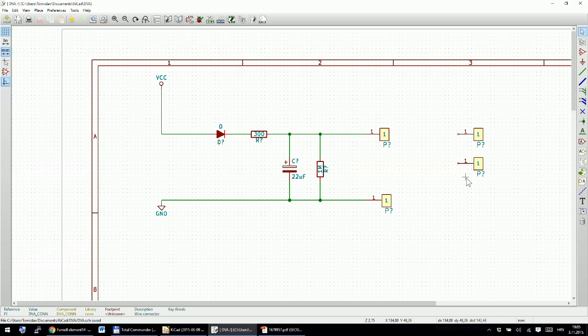Alright. So also, if you need to move components, you just grab them like this and move them. So each time you do a square, you do this rectangle around your components, they will stay attached to your cursor, so you can move them anywhere. Let's say right here. Okay, I will not connect directly a wire to VCC and to ground, because I just want to show how you would do it if this was a bit more complicated schematic.